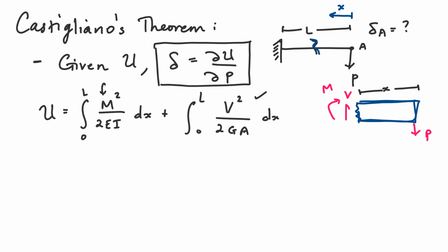Okay, so summing the forces, we see that V is equal to P, and when we sum the moments, we see that M is nothing more than Px. Okay, that's the shear and bending moment.